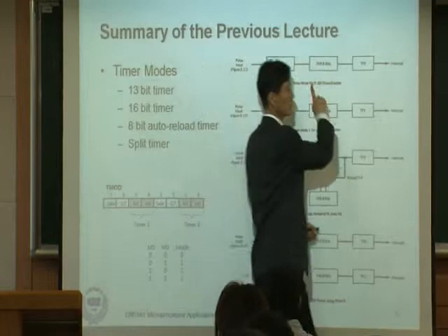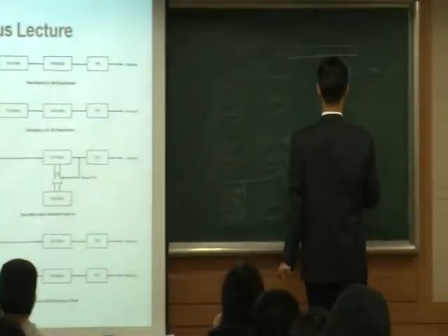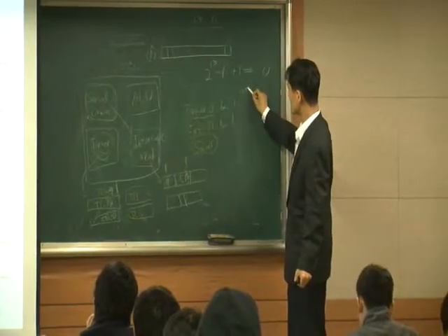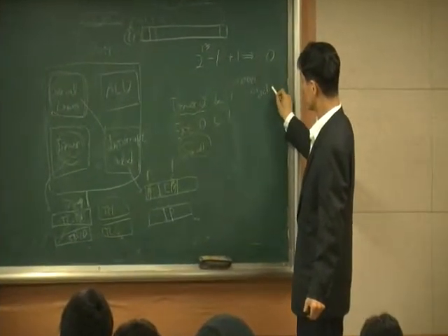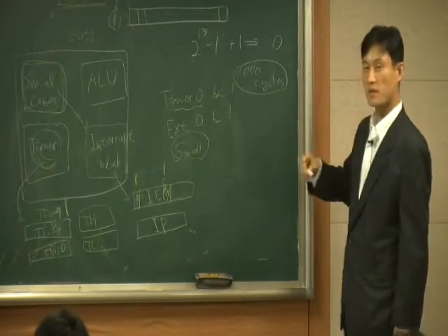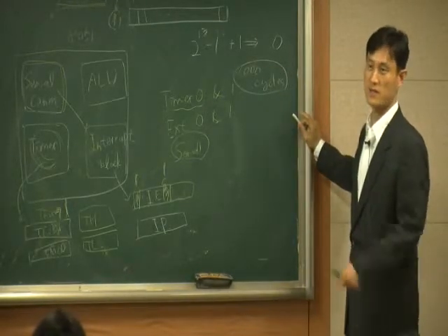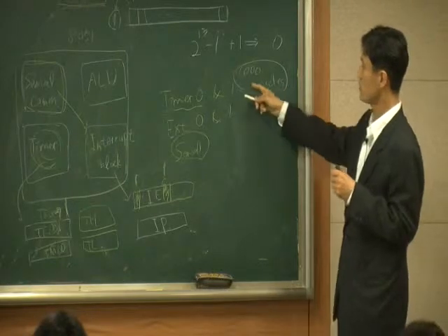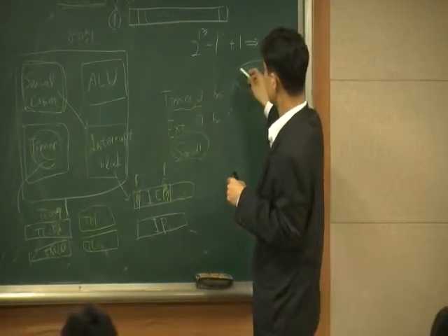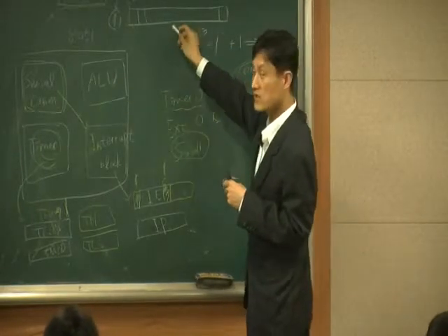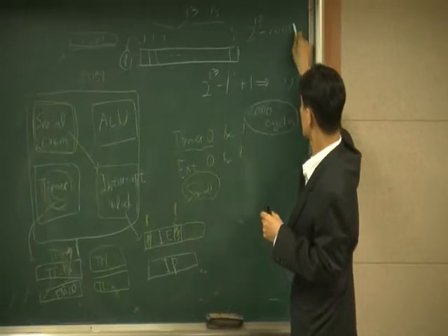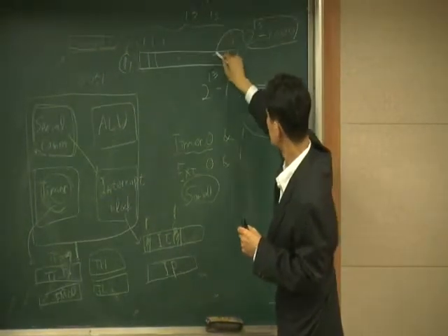And this happens after a certain number of cycles. So what you want, for example, is to count 1,000 cycles as an example. Sometimes maybe you want to count 2,000 cycles, depends on you. So suppose that I want to count 1,000 cycles, then you want to program this value as an initial value here.